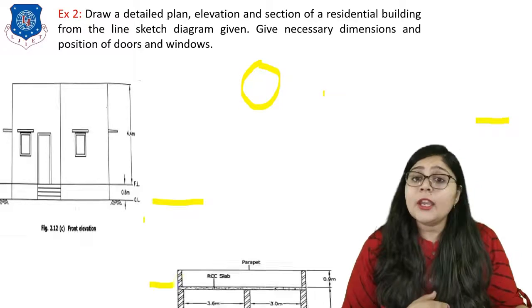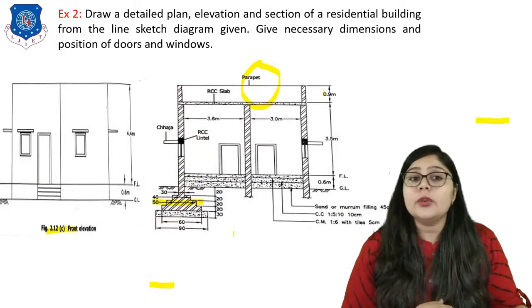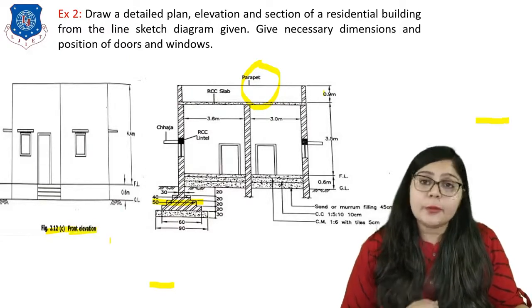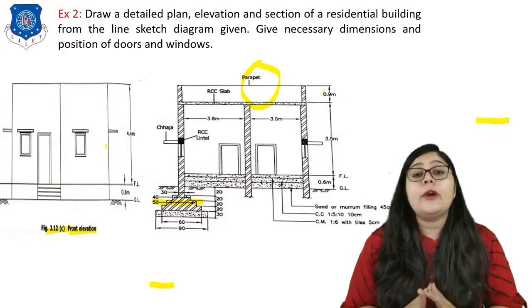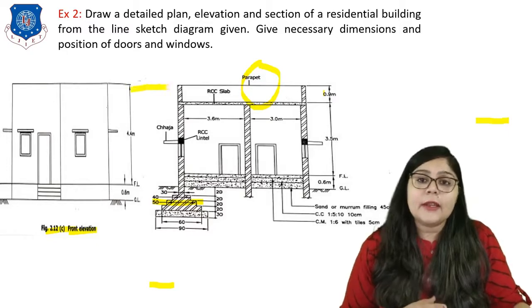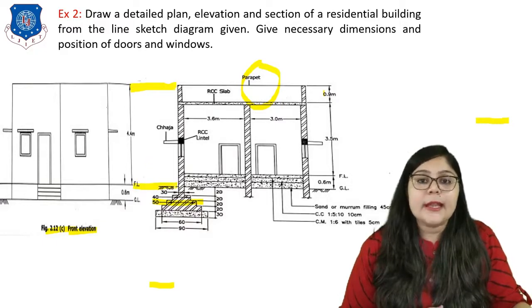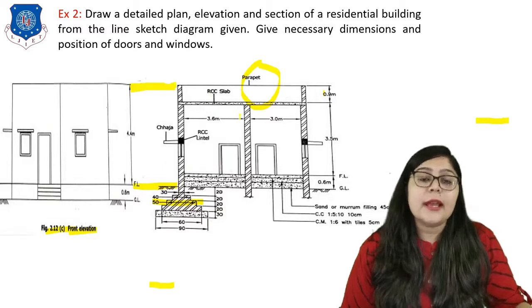Now, if I have to arrange the elevation and section, here you can see that the elevation we can get from the plan, right? So here the height we identify when we look from the front side, and as we extend these lines, I want to say like this, right? As in the previous example, these lines are extended in such a way that we can get this section from this elevation.